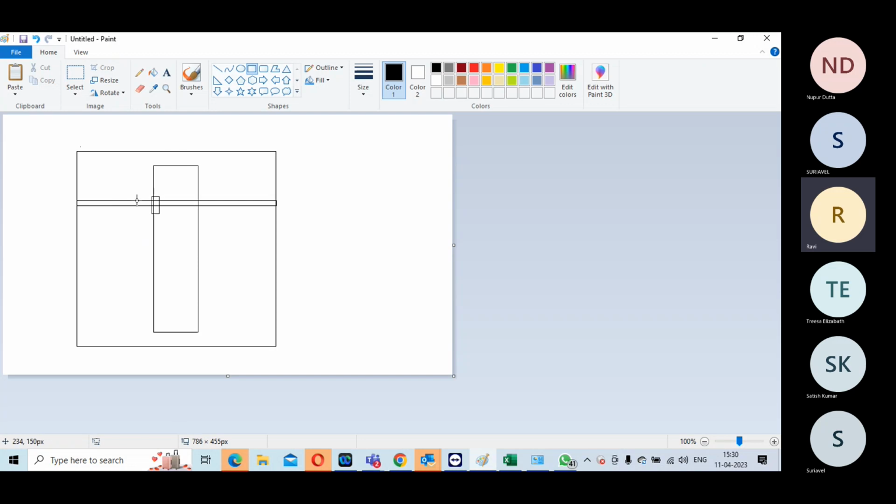But if it has an M1 power rail, this circuit row has to have a breaker cell for the always on. This one is also connected, but not to these things, because this power is broken over here. This is a complete always on power. So in the case of the other methodology, the always on cell will not have an M1 power rail; VDD and VSS will not be there. That will be a pin.